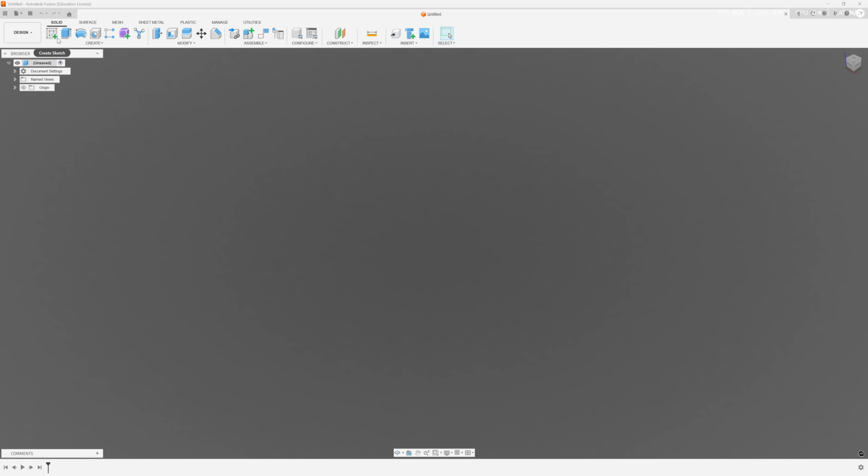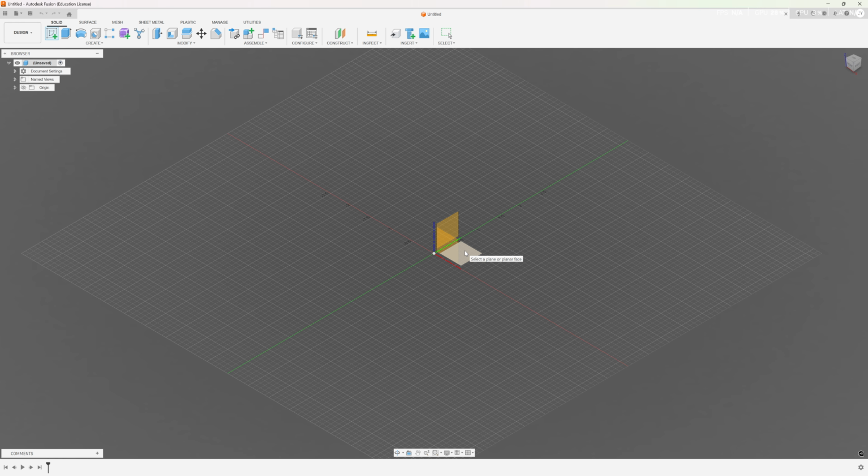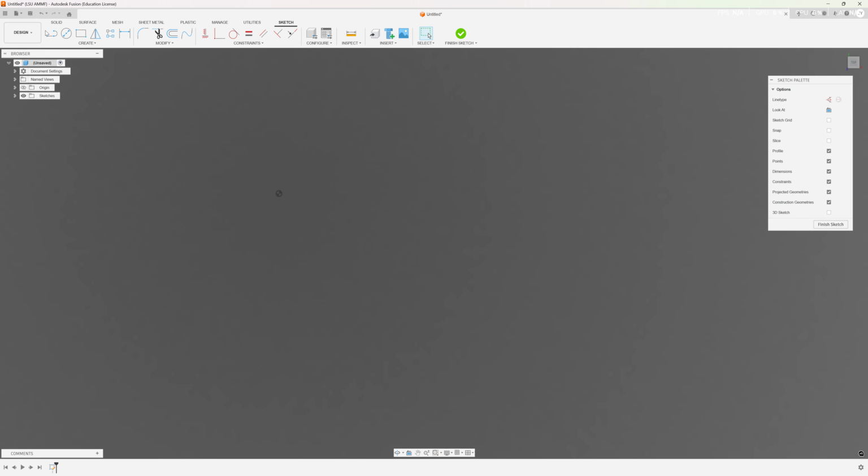So we are going to start with creating our first sketch, which here we're going to select Create Sketch. I'm going to select my XY plane, and then I'm going to draw the rough shape of my C-clamp body. Now I'm going to start by clicking the origin point. So I've clicked the line. Now I'm going to go to my origin point, so I'm fixed to my origin. Draw my first line, angle,